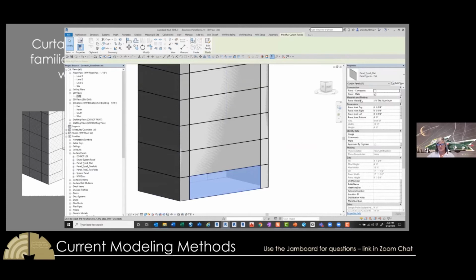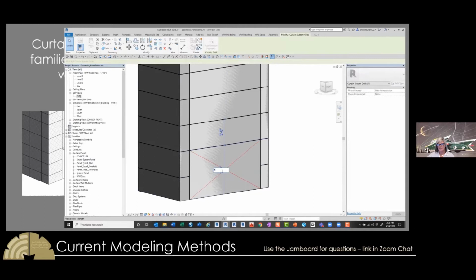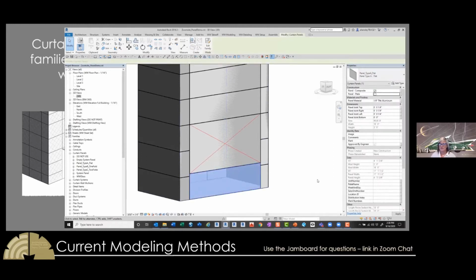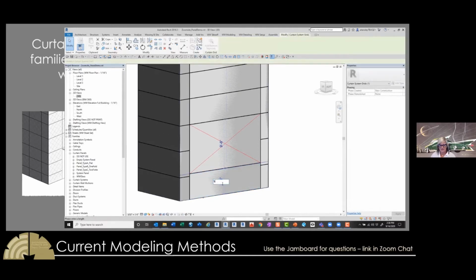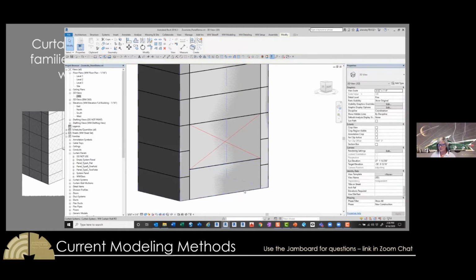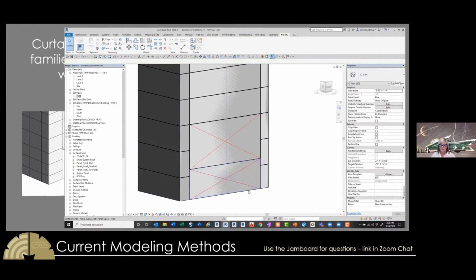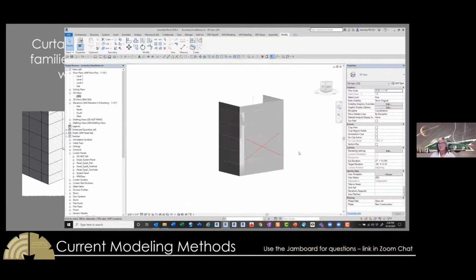The last thing to note, it's set to plate panel by default, but plate panel and composite panel have different maxes for before it gets more expensive. So you can see right now I select that smaller panel. Set that to plate, make it 5'10". So when it's plate, it's fine, but if I select it and switch it to composite, it now exceeds the composite standard size. I mean, it's met the maximum. It doesn't mean we can't get it. It just means it's going to cost more money.